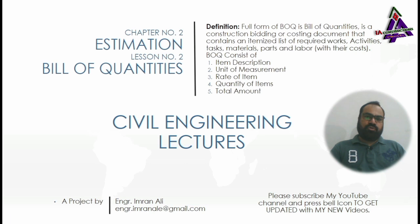An estimated BOQ is provided by the client, which is normally called the engineer's estimate. It is further submitted by the contractor along with quoted rates of all items or activities of the construction project, above or below the engineer's estimate according to feasibility and market rates.